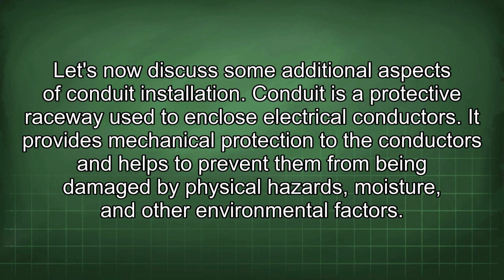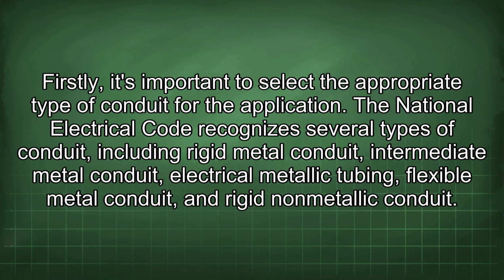Conduit is a protective raceway used to enclose electrical conductors. It provides mechanical protection to the conductors and helps to prevent them from being damaged by physical hazards, moisture, and other environmental factors. Firstly, it's important to select the appropriate type of conduit for the application.